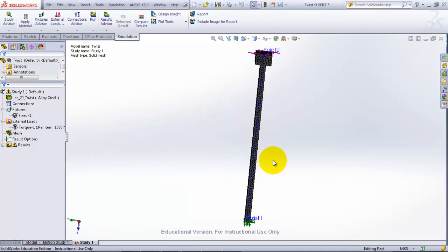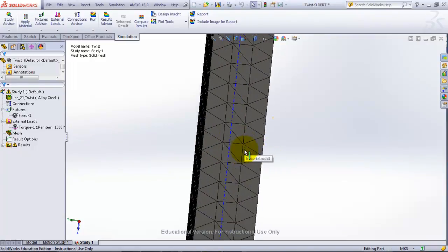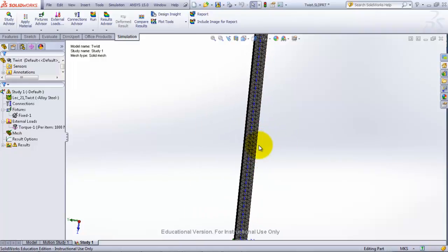All right. And what I'm doing is, if you look across the thickness here on the side, in the first case we had essentially one element across. With 5 millimeters, we would have had only two elements. Now at 3.33 millimeters, we can get three elements across. And so that's what I'm attempting to do here: I'm changing that value based on how many elements I can get across that space if I reduce it the appropriate amount.